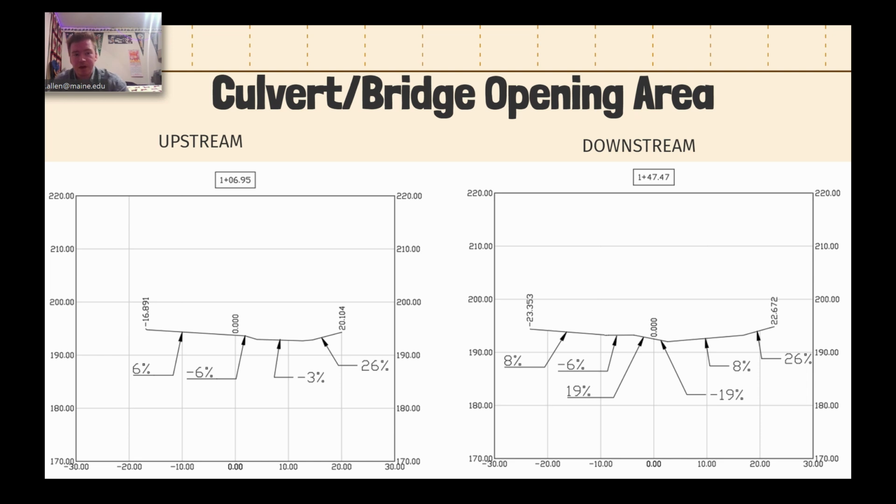The channel slope was calculated from taking the low point of the nearest cross-section upstream of Mount Pleasant culvert and the low point of the first cross-section after the culvert. Using this, we can create a proper channel slope where the stream would like to flow, and then we can lay our culvert in such a manner. The roughness coefficient used for our designs was 0.04, since it produced the largest values. The Manning's roughness equation was used in our process to calculate flow values that can be seen based on both upstream cross-section values.